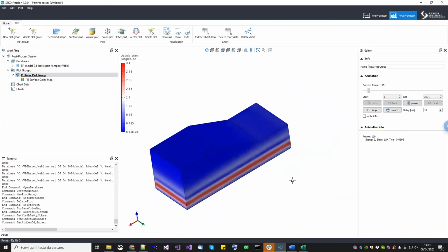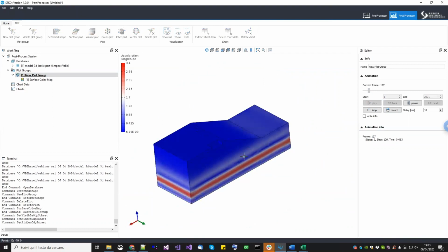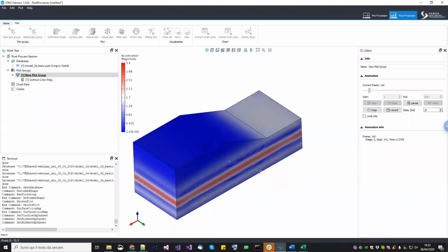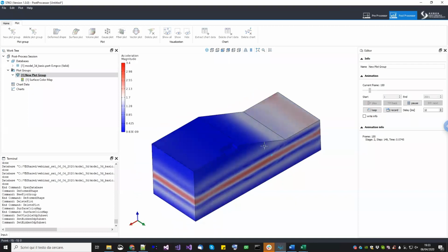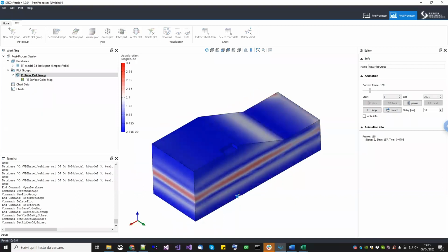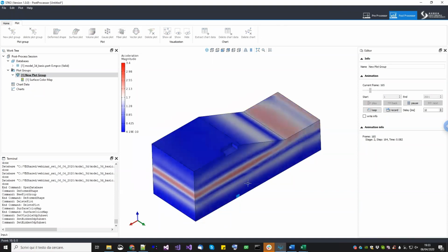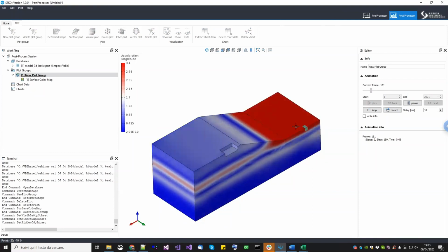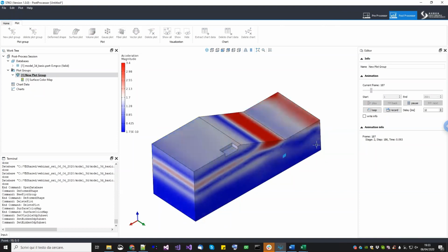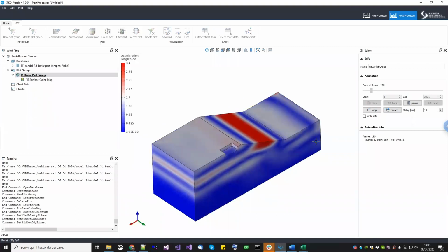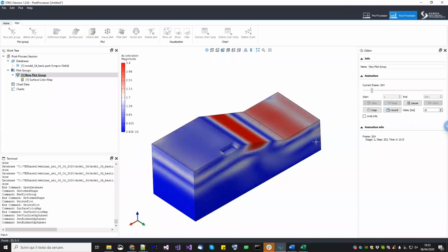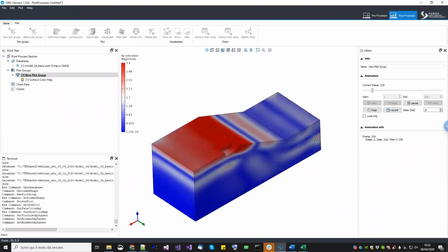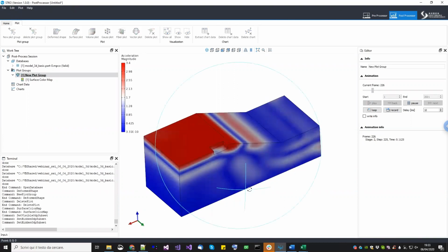Okay, so you will see the wave propagating from the bottom. Why did I fix it to the top value? Because in this case, it will be easier to visualize when the waves will be reflected and when they will go almost to zero. Of course, keep in mind that the Lysmer-Kuhlemeyer boundary will absorb these outgoing waves, but not perfectly, because if the incident angle is not exactly aligned with the Lysmer-Kuhlemeyer condition, something will be reflected, but it's the best approximation that we have now in OpenSees.